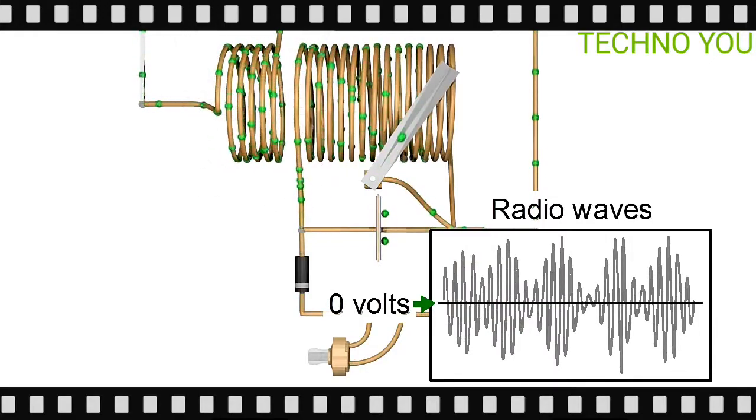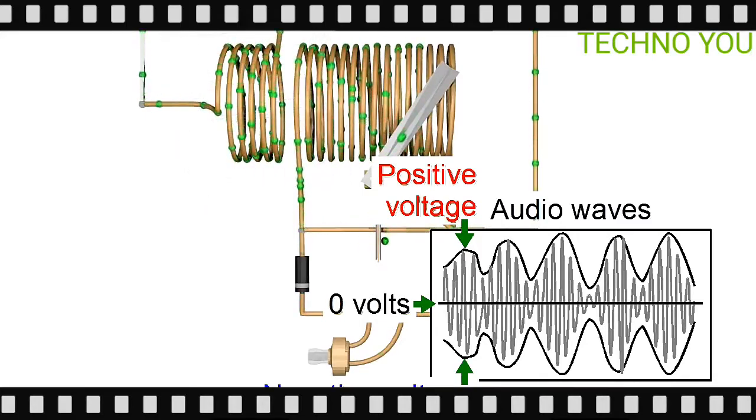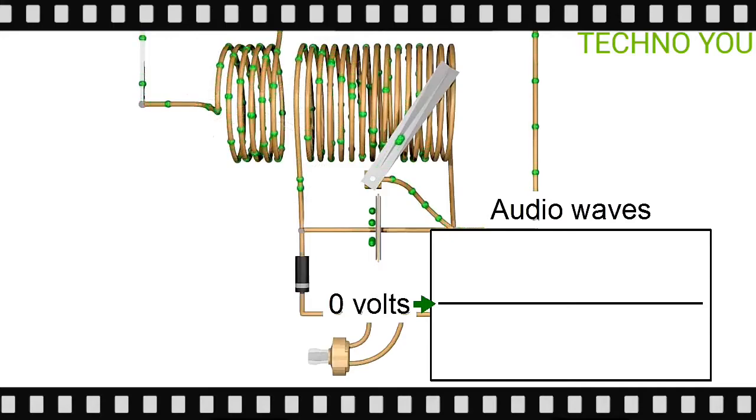Looking at the radio waves, here the voltage is positive, then it's negative, then it's positive, and so on. So if the crystal could react fast enough, it would react to that. But as we said, it isn't fast enough. Looking at the audio wave that it can keep up with, the voltage is positive here, but it's equally negative at the same time. So the net voltage is 0. And so the earpiece would see 0 volts all the time and do nothing.